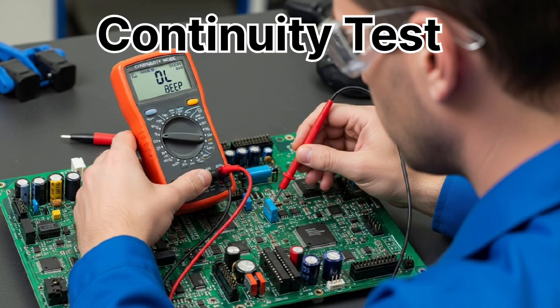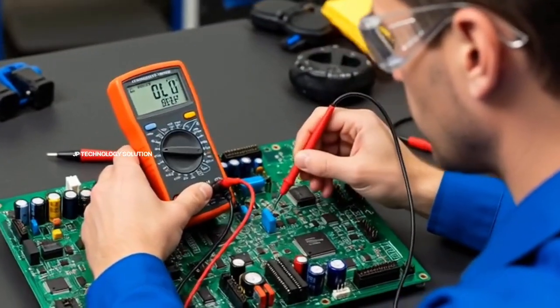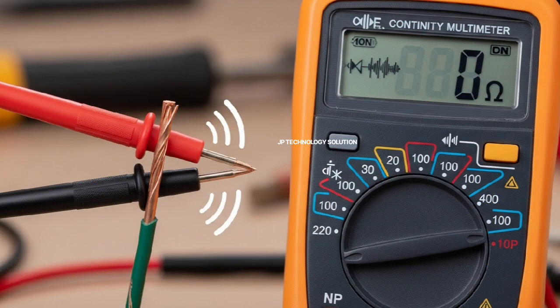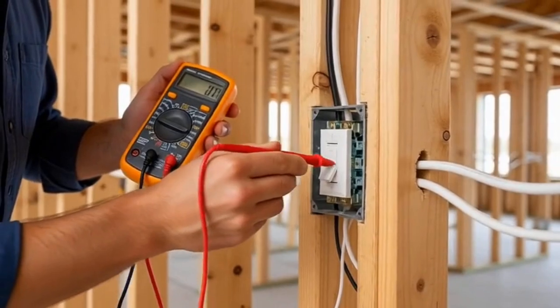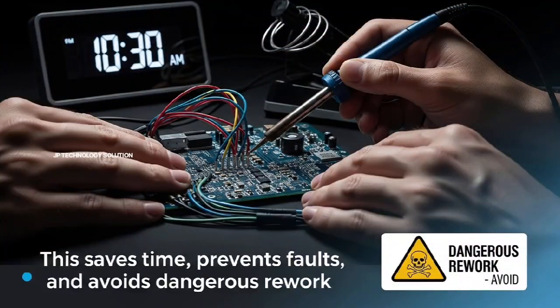Question 22. How do we perform a continuity test? A continuity test ensures there is no break in a cable or circuit. Steps. Set the multimeter to continuity mode. Place probes at both ends of the conductor. If the circuit is continuous, the meter will beep or show close to 0 ohms. For example, if you are wiring a house and want to confirm that a light switch is connected properly, you can perform a continuity test before energizing the circuit. This saves time, prevents faults, and avoids dangerous rework.